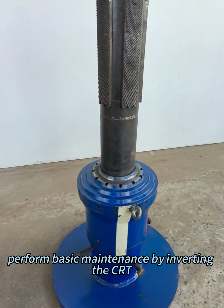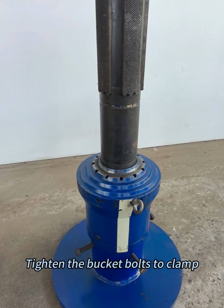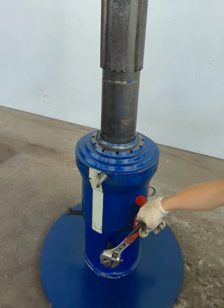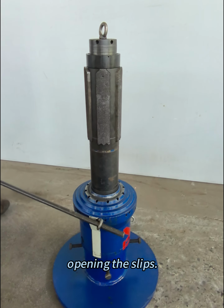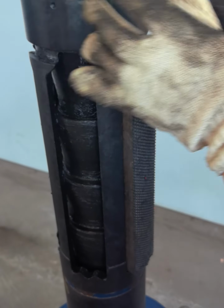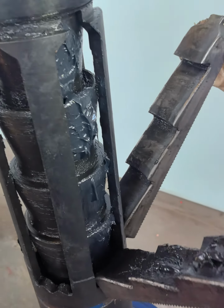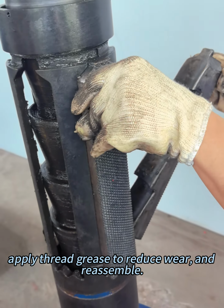After each use, perform basic maintenance by inverting the CRT into an installation bucket. Tighten the bucket bolts to clamp the CRT's locking sleeve. Use a pry bar to rotate the anti-collision plate clockwise, opening the slips. Clean thoroughly, apply thread grease to reduce wear, and reassemble.